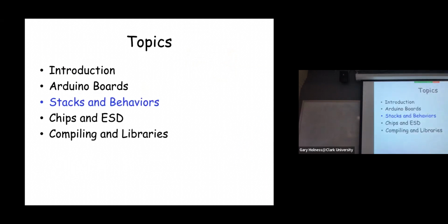And so one of the things that's really, really important to become familiar with is electrostatic discharge, or ESD. You've ever walked someplace and you shake someone's hand or touch the doorknob, zap, you get a little shock of electricity, right? Nothing major, nothing painful, nothing detrimental, but to a chip, that's death, right?